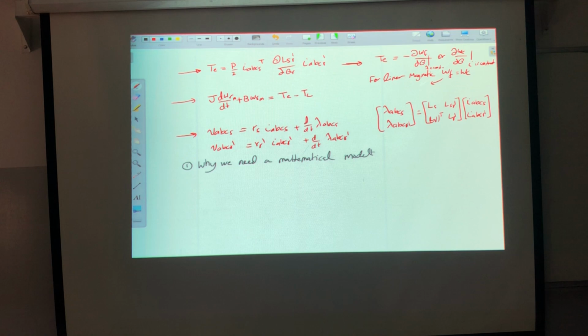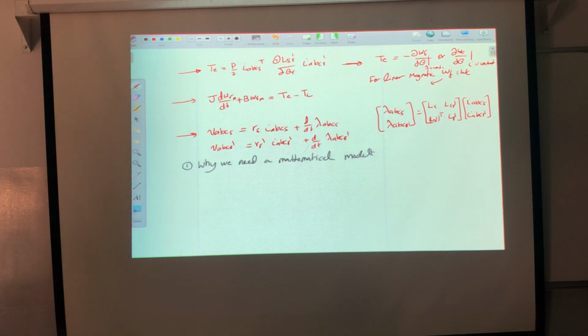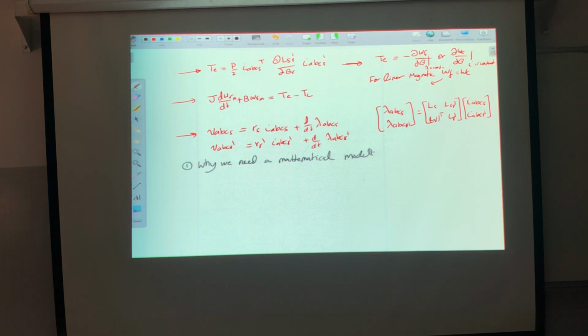So the first thing you should do is guarantee the performance in simulation. After that, you will take the parameters, go to the lab, and implement it. You will need later on to do tuning. Why? Because there's a mismatch between the mathematical model and the physical system. One of the main mismatches is the approximation. We are doing approximation, by the way. We are assuming a linear magnetic circuit, not a linear system. It's a linear magnetic circuit, although it's not.